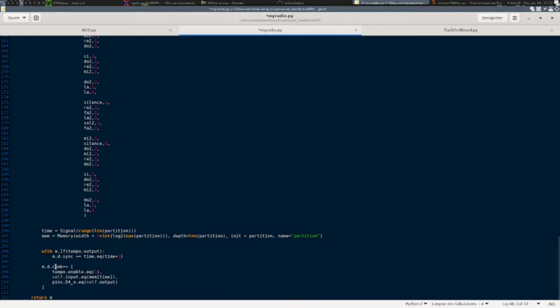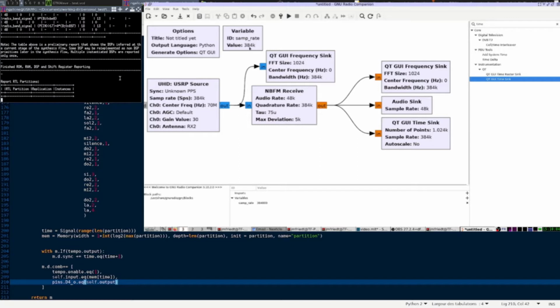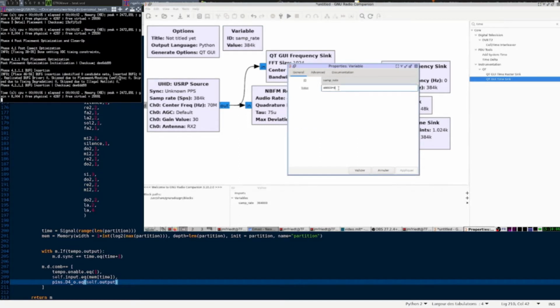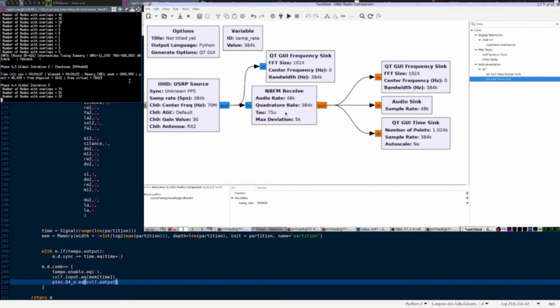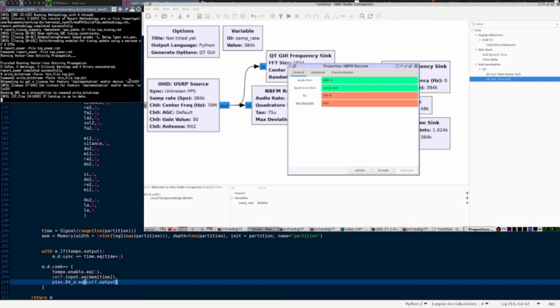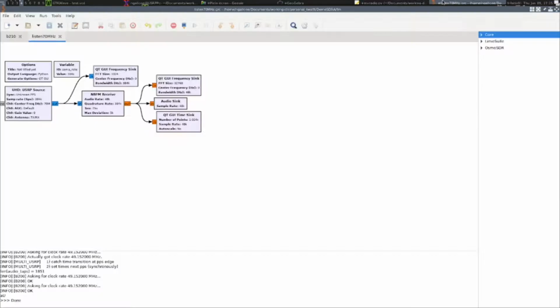And so you add the last rules to make this music being played by the FPGA. So let's look at it. And while the bitstream is synthesizing, here is a flowchart for radio decoding. We select the data rate, integer multiple of the output audio rate, and the narrowband FM receiver outputting 48 kilosamples per second. Alright, so we open GNU Radio.